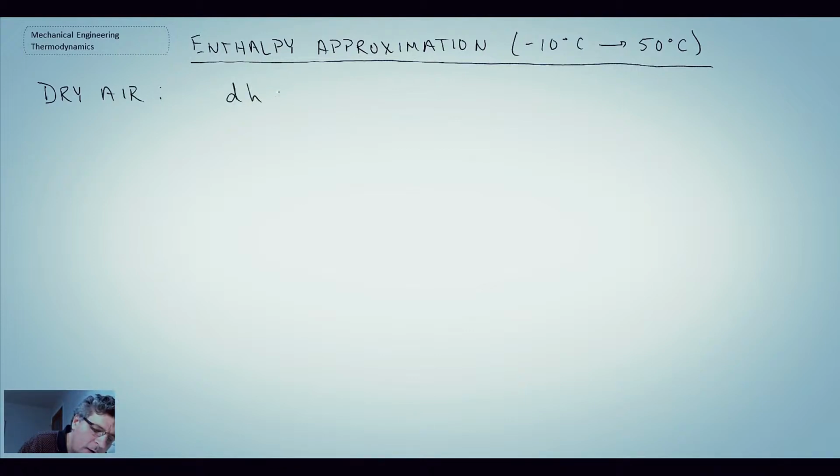And if you recall, we said that enthalpy can be calculated using this equation here. Sometimes Cp changes if you have variable specific heats, but what we want to do is integrate that. And so what we'll do is integrate between 0 degrees Celsius and up to some arbitrary temperature not yet determined.